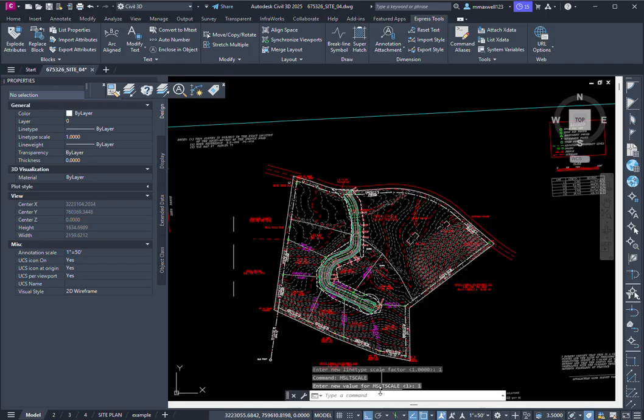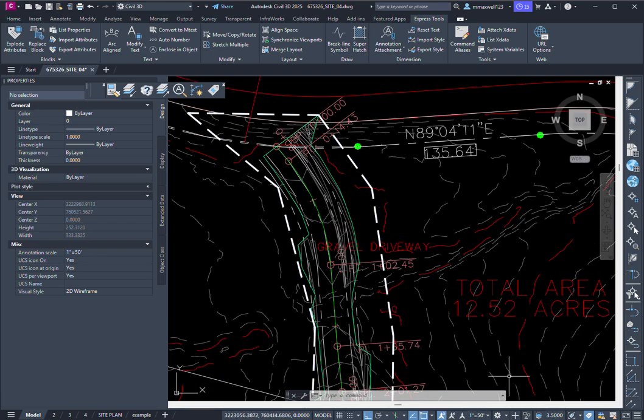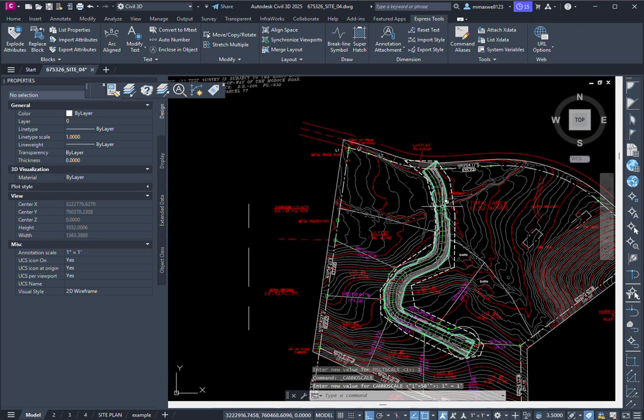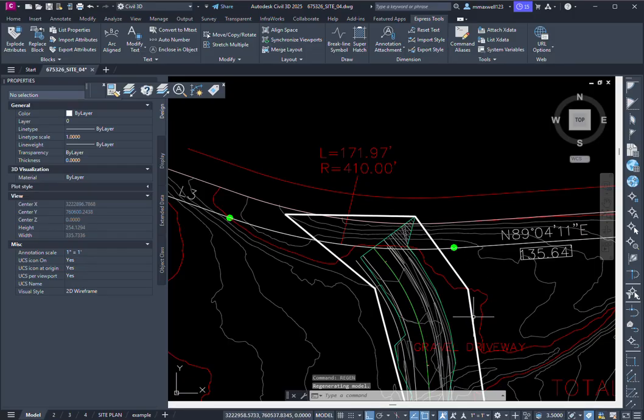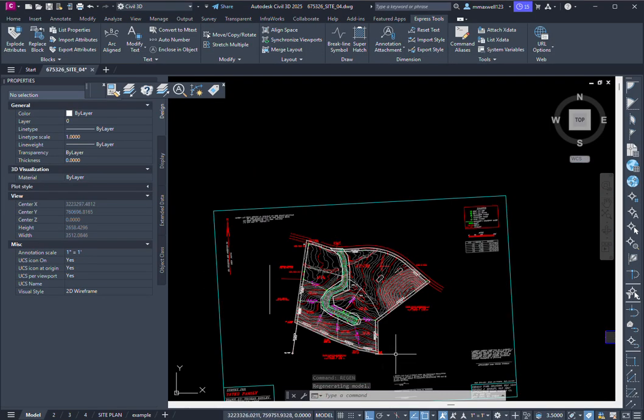And what MSLT scale is, once you have that turned on, what you see on the screen will be what gets printed in all cases. If you don't have that turned on, it's a little difficult to work on the drawings without having these patterns. If that's not turned on, your drawing will look more like this, where the patterns disappear, just 2 continuous lines.